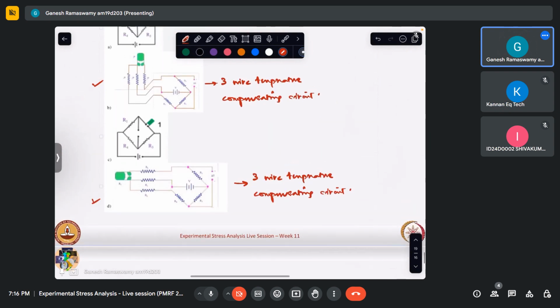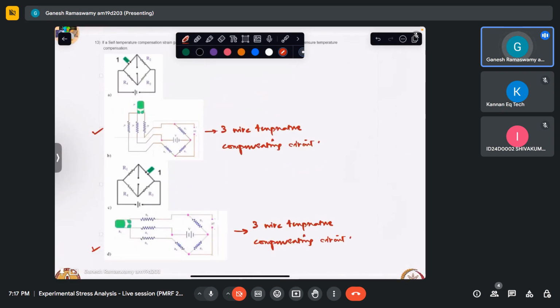So this is how we address temperature issues. As we can see clearly, although the strain gauge is very effective, temperature has a very major role to play in such problems. So at site also, when we are making the measurement, for example, if they are making strain measurements on rails, in order to nullify the effect of the inherent temperature there, they would also have a test piece of rail placed on the side, which is not connected to anything, and they would be making measurements of strain on that very piece also, in order to nullify the effect of the ambient temperature on the strains.